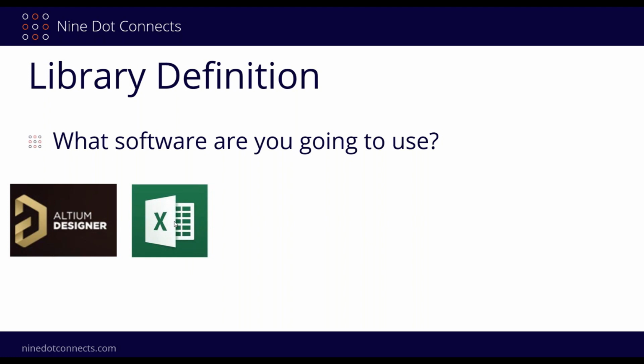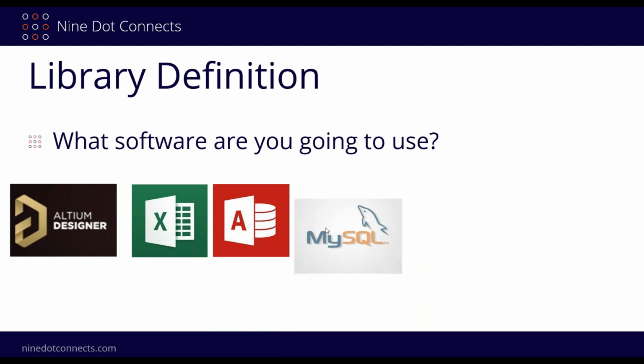So what are the other products out there? Well, there's Excel. Now, Excel is not the best product for it, but a lot of people like to use it, and we use it all the time as a temporary database. That's what you're going to see here today, because it works really well in getting us to the ultimate goal of getting it into a container. But things like Access or even SQL are products that you can certainly use, and Altium can interface with them. But they do put a lot of burden on you, because not only are you trying to maintain the components, you're also trying to maintain the actual database itself. Now it's up to you to create the tables. Now it's up to you to maintain the parameters. Now it's up to you to create the forms that people use so that the data entry is done properly. And it's going to be up to you to clean it up when they don't do it properly.